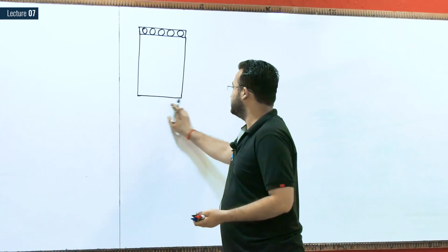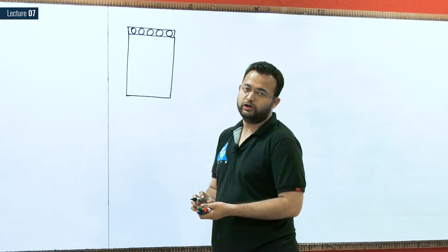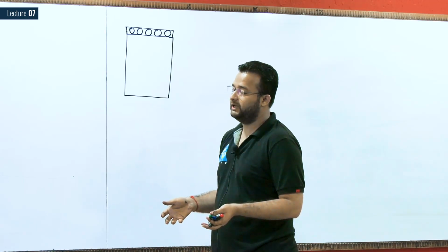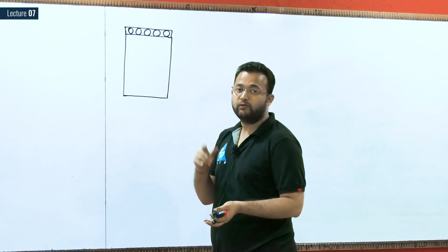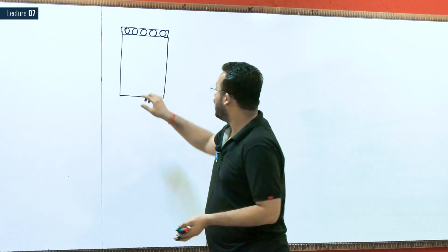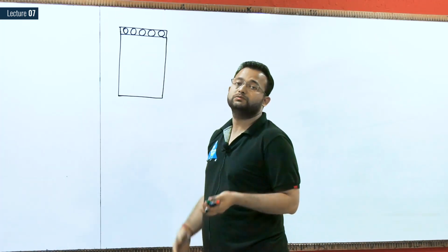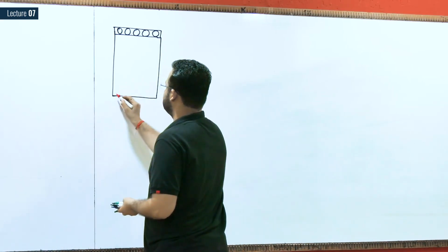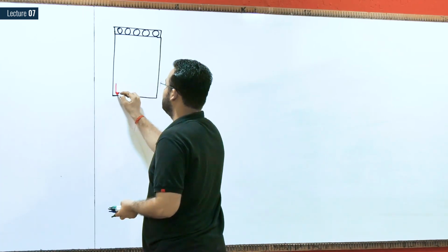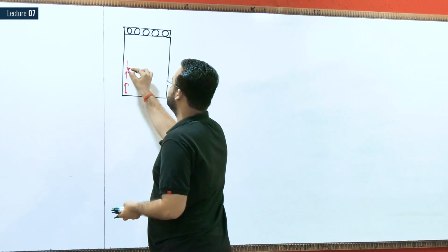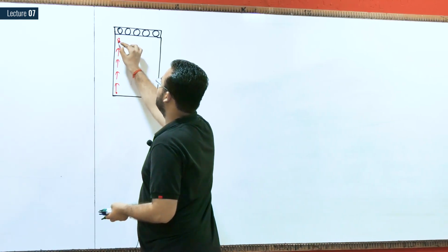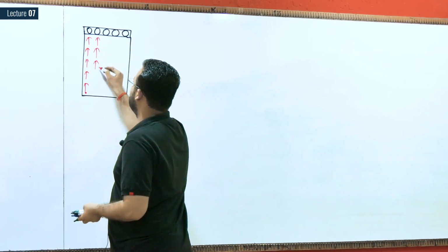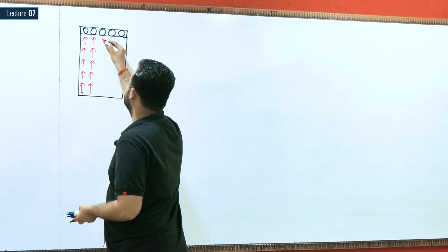Here we have not kept the porous plate at the bottom. Then what will happen? If you do not place the porous plate at the bottom, the water will not flow in the downward direction. All the water will reach in the upward direction, because water has to drain out. So water is draining out only in vertical direction. The water molecules which are present here will cover this distance and reach near the porous plate, and then they are draining out, something like this.